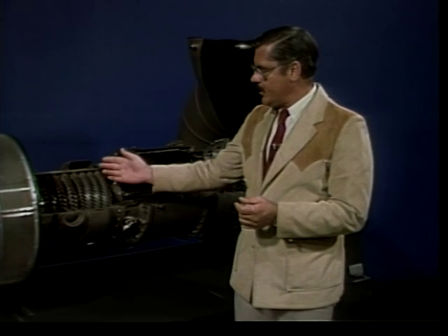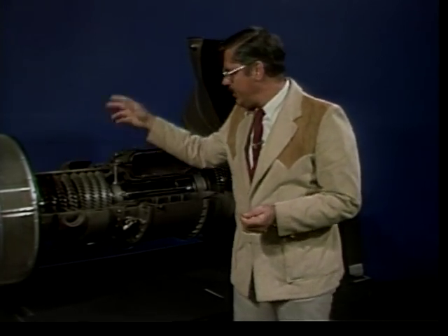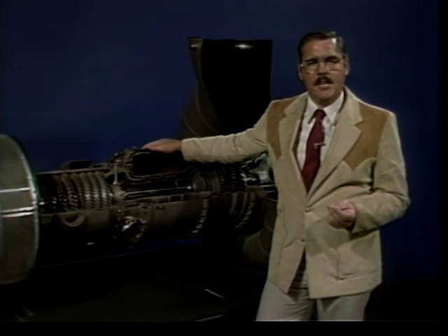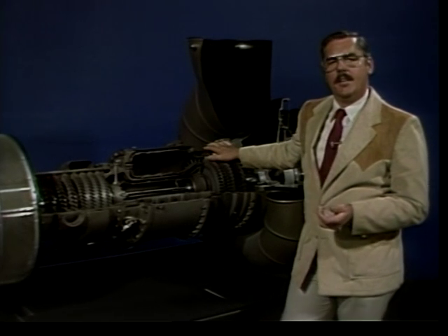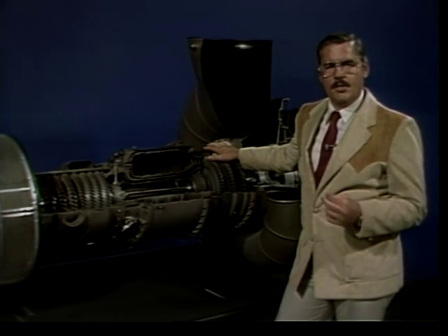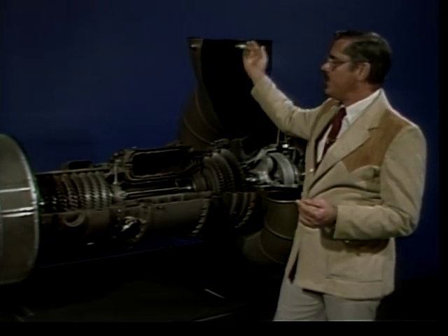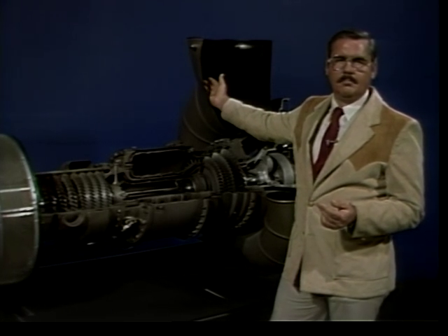In the turbine engine, the unique relationship between pressure and velocity explains many operating principles. In the compressor, the air is slowed and compressed. In the combustor, the air is heated and then expanded. In the turbine, the air is speeded up to be used to turn the turbine wheels and then is exhausted to atmosphere.